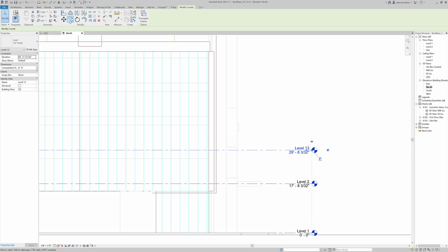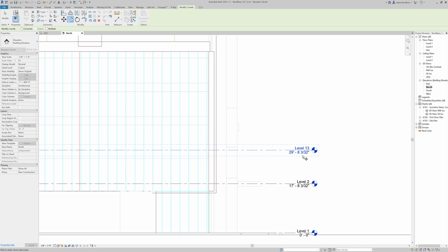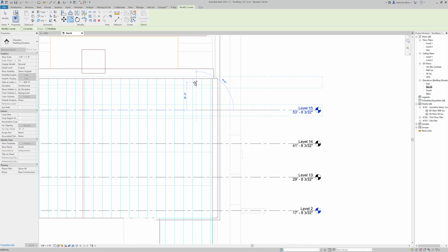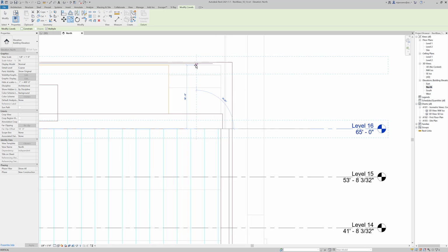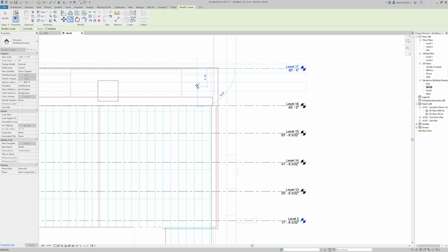But anyways, let's go ahead, and you can see that I've actually made some levels here, so it's not going to auto-populate with the name. And you might want to turn multiple on. So what this will allow you to do is select multiple or copy multiple things at one time, and I'm going to choose the roof here, and you can see it wants to snap in the vertical lines, so try and keep them all arranged.